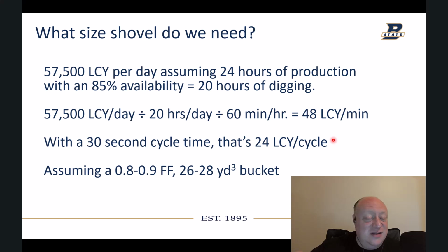We can convert that 20 hours to minutes, and we get 48 loose yards a minute with a 30-second cycle time. That's 24 loose yards per cycle. Then if we assume a 0.8 to 0.9 fill factor, you're looking at a 26 to 28 cubic yard bucket.